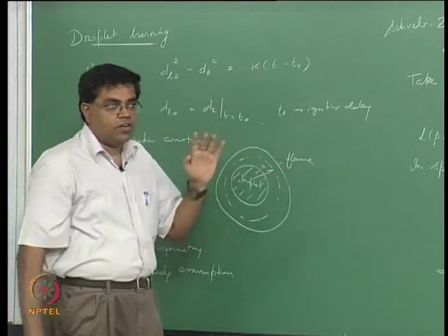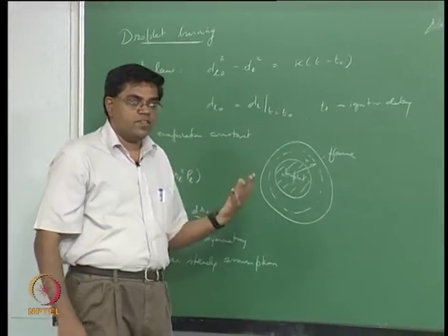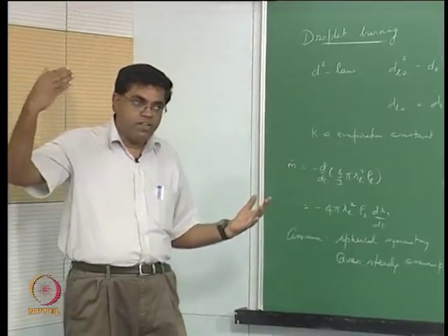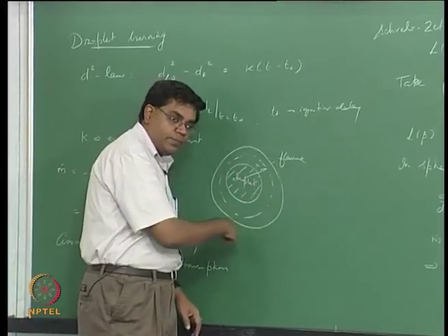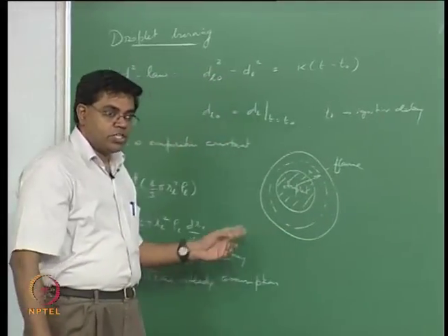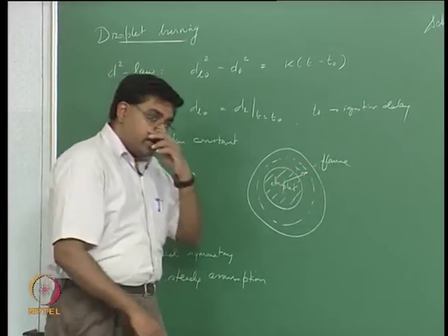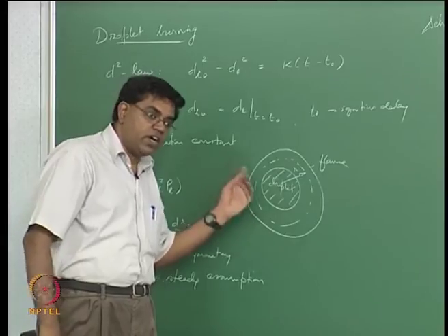Of course in the solid rocket you don't really have atmospheric oxygen, you have oxidizing species in the form of water and carbon dioxide and so on, which carry oxygen atoms in them, and they mix and then form a flame, and the product of combustion is Al2O3, right, in gaseous state, because the temperatures are so high that it would be even higher than the